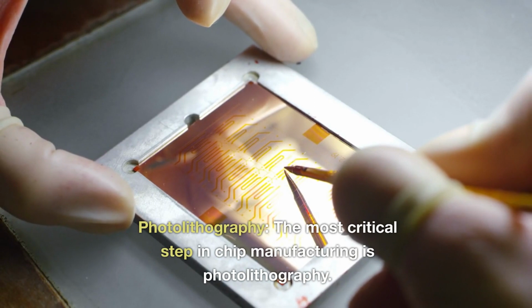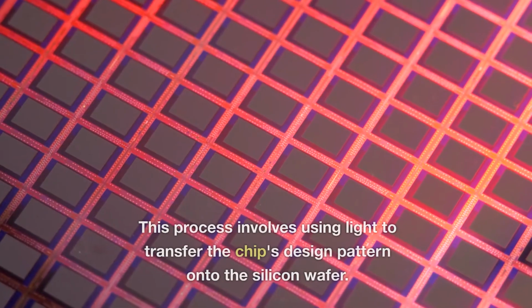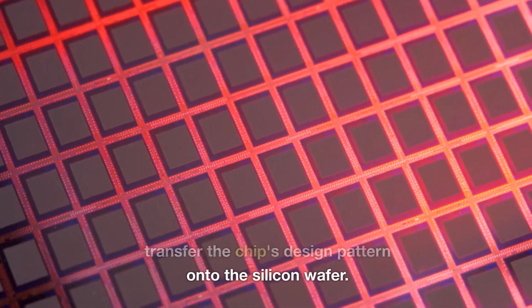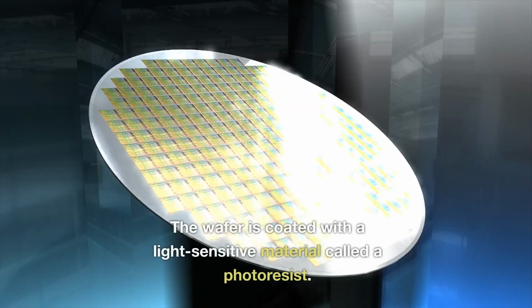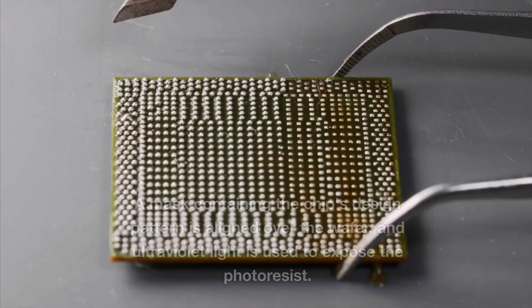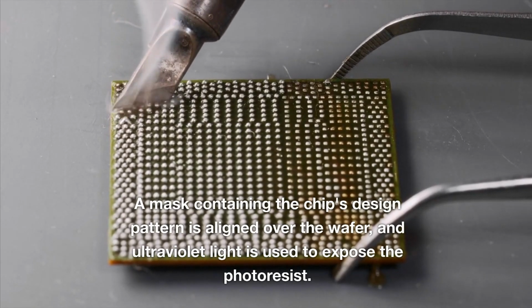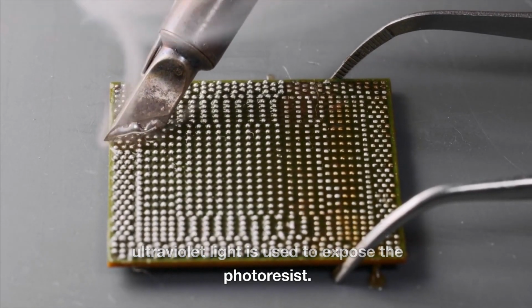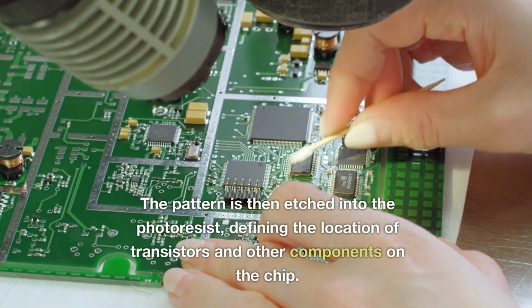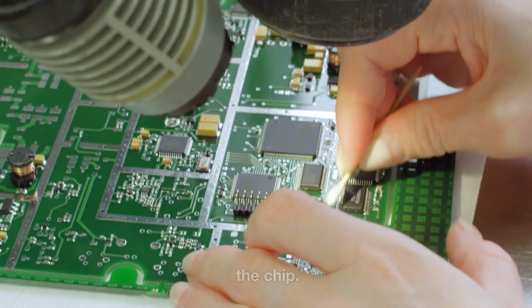Photolithography. The most critical step in chip manufacturing is photolithography. This process involves using light to transfer the chip's design pattern onto the silicon wafer. The wafer is coated with a light-sensitive material called a photoresist. A mask containing the chip's design pattern is aligned over the wafer, and ultraviolet light is used to expose the photoresist. The pattern is then etched into the photoresist, defining the location of transistors and other components on the chip.